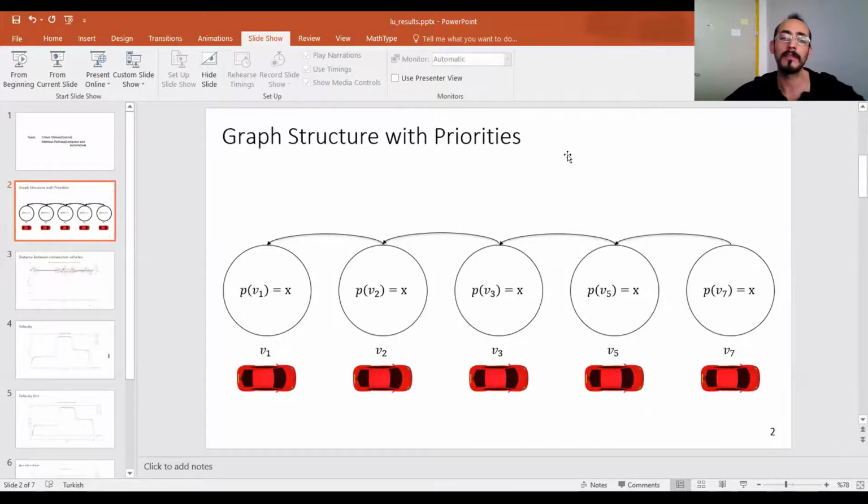We somehow modified the centralized MPC file so as to include a reference trajectory for vehicle 7, which is the highest priority vehicle, and the others were the same as the centralized MPC case, but we partitioned into individual cars. So each individual car performed its own MPC optimization, and it produced its own control input.